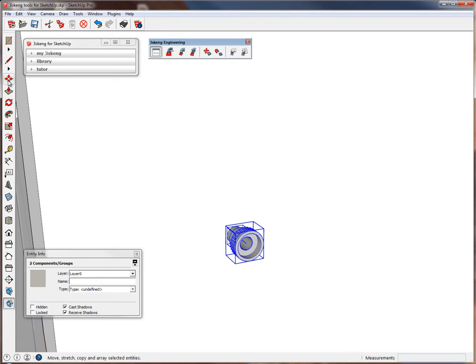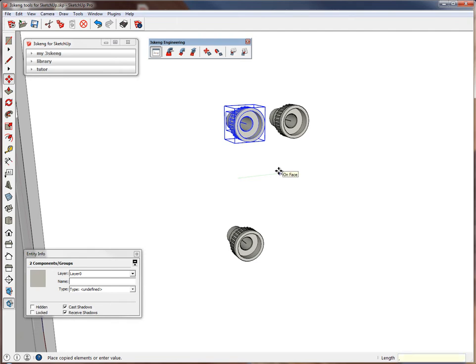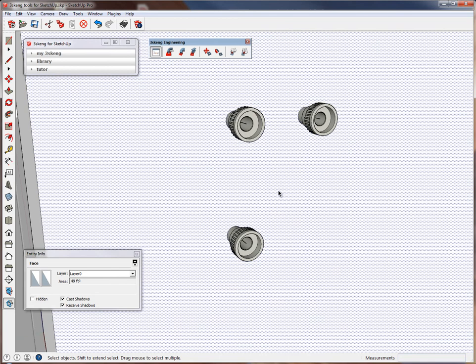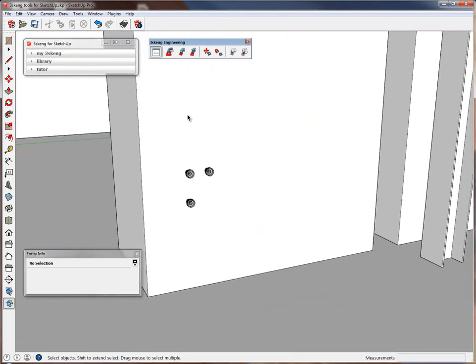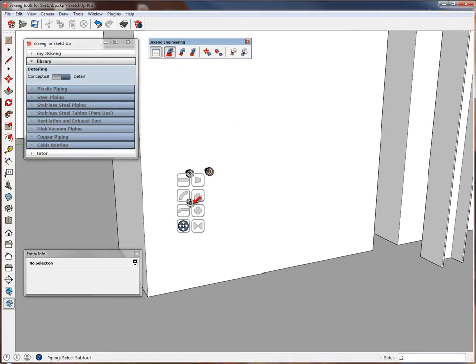We will copy the straight piece and the union to be our future cooling water supply and return. Now we can exit the component. In the detail mode, you don't have to select the pin outside visible for components because it's already predefined that way for all detail connectors. But let's continue with the sloped drain.